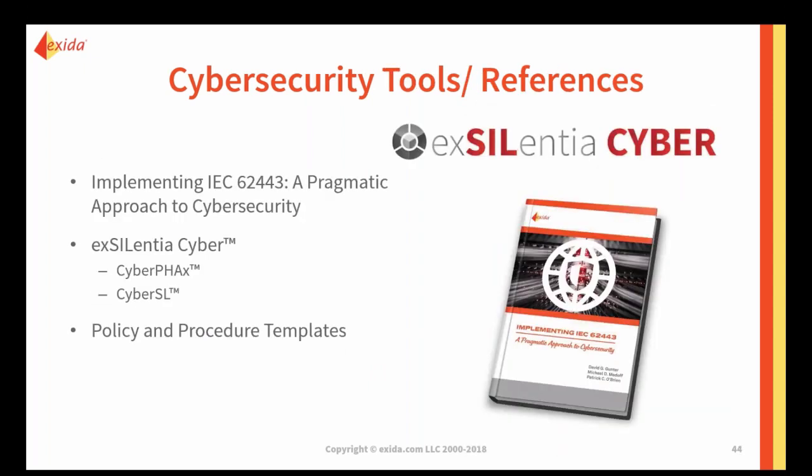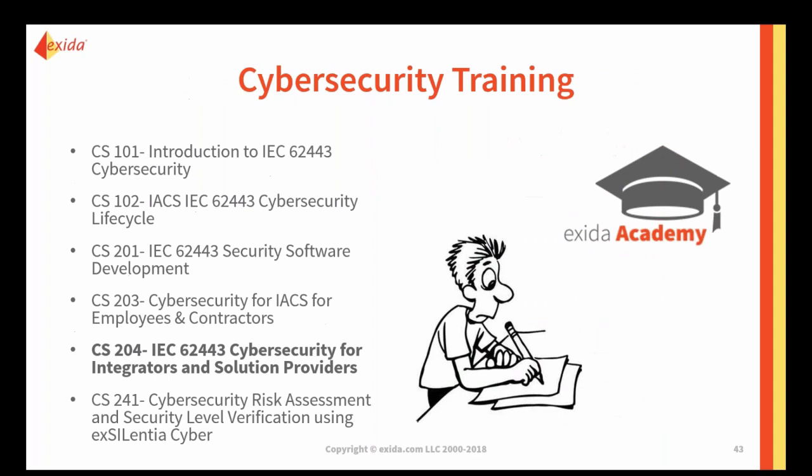There are a number of cybersecurity tools and references. The book Implementing IEC 62443 does a really good job of looking at how to take those requirements from the standard and understand how to apply them. There's also the exida tool, which has a cyber module that can support cyber risk assessments and cybersecurity level verification. And then there are also a number of policy and procedure templates that can help with developing the security program.